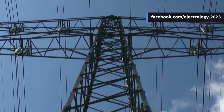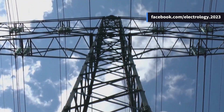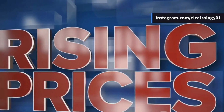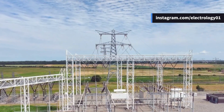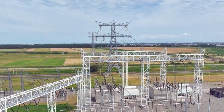So, there's a point, a particular voltage, beyond which increasing voltage doesn't give you more savings. Instead, it just adds to the cost. This ideal voltage, where the combined cost of everything, conductors, insulators, transformers, switchgear, and terminal equipment, is at its lowest, is what we call the economical transmission voltage.